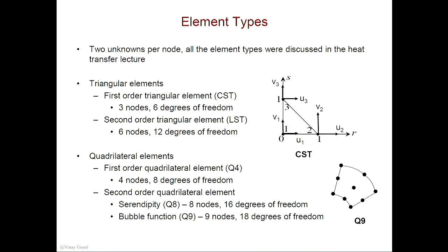The element types are the following. So you have a triangular element. This is called a constant strain triangle because the strains are constant across the triangle. Two unknowns per node. That's also known as the first order triangular element. In Abaqus, don't quote me on this. Actually, can't remember. No, I'm sorry. Yeah, I told you about them. It's CPS3 for plane stress, CPE3 for plane strain.